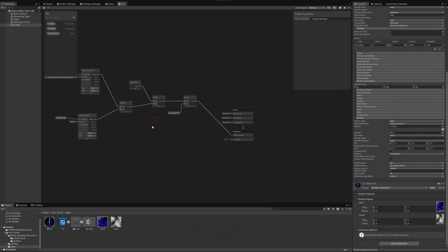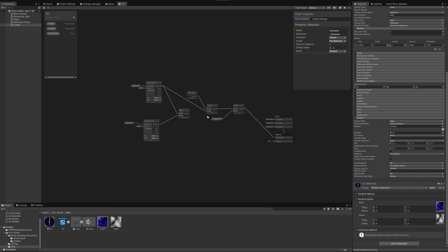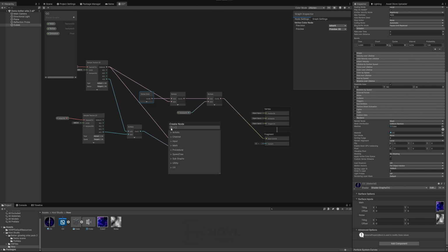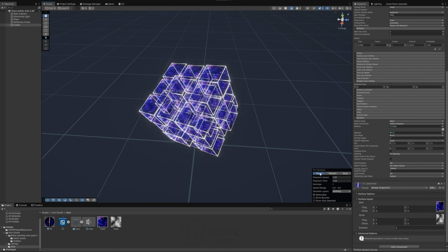Also, you can actually add only main texture to base color and multiply alpha channels for transparency to add it to alpha channel. So also multiply it with vertex color, but with also alpha channel. Use split node for this. I will change places for better view and press save and let's see the result.